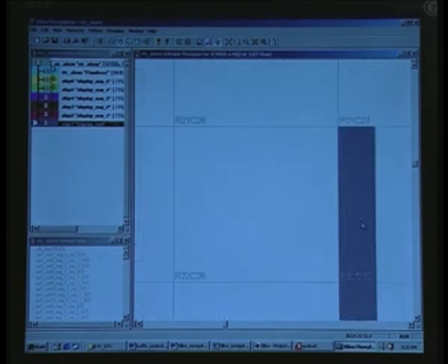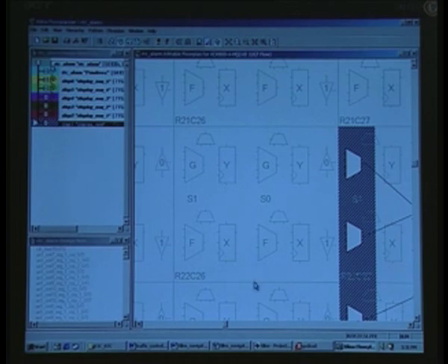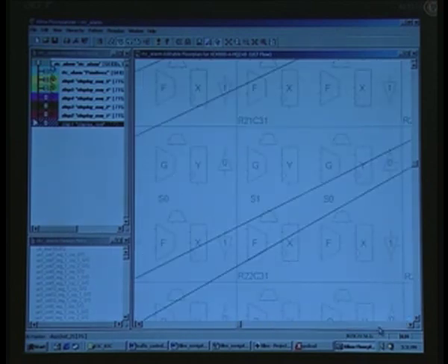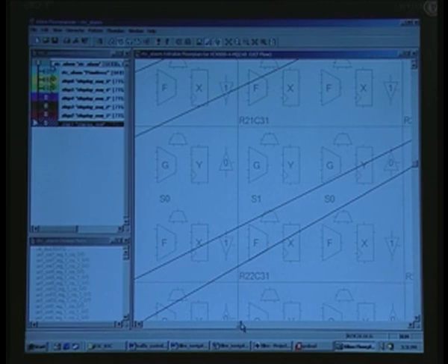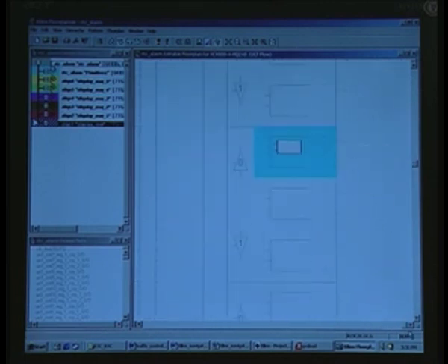and suppose you want to relocate this one from here to somewhere else, let us say here, you are free to do so. So, you have the flexibility of changing, that is vetoing Xilinx's place and route, what it has already done. You can overrule that one and place it elsewhere, and similarly you can go to a particular pin, and you see where the lines are precisely going to the pins. For example, one of the pins may be somewhere here. Let us see, there is a pin here, but unfortunately it is not connected to that, I think.